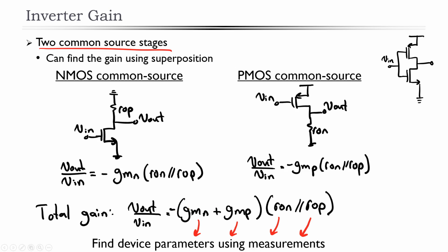But what if you're inventing a new device? What if you're making a new transistor? Then you have to go ahead and measure the characteristic of the transistors and then extract the small signal parameters. And this is a link that is mostly not well understood by the people who are learning this material for the first time: the link between the DC characteristic of the device, which leads to small signal parameters, which can be used to calculate gains of amplifiers. So let's go ahead, measure the DC characteristic of these devices using the Keithley source meters again, and then extract these parameters out, which will be a really interesting thing to try.